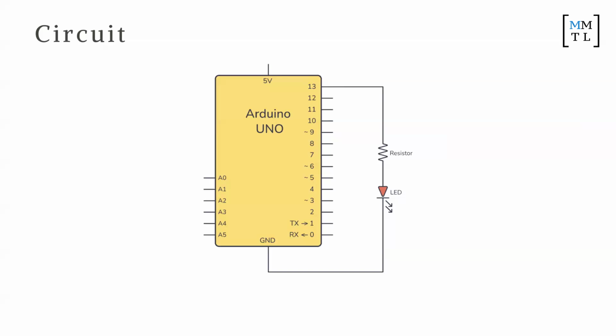Okay, then we want to do this first. Place the resistor first, 1, 2. Now just recall that there is no connection to the 5 volt there. So just make sure that there is actually no connection from 5 volts from your Arduino.